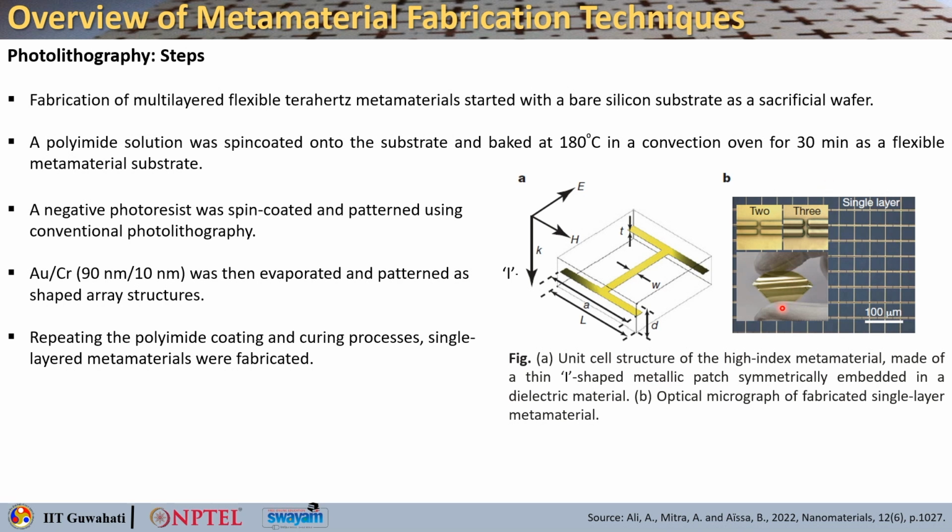The curing of polyimide layers was conducted at around 350 degrees centigrade using an open-ended quartz tube furnace under an inert atmosphere to convert the polyimide acid into a fully aromatic and insoluble polyimide.